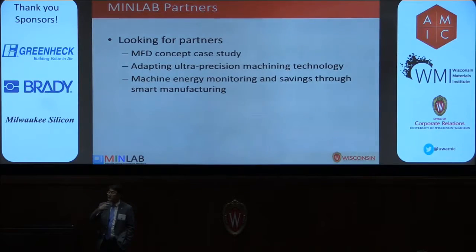Right. So his question is what kind of pattern limit we can reach with this ultra precision machining compared to what photolithography and semiconductor manufacturing can do. Basically, yes, we are reaching that level actually. Some of the features we can create are from a few microns to tens of nanometers. In terms of feature size, we go down to tens of nanometers. But in terms of surface quality, it actually beats the semiconductor industry now, at the angstrom level.